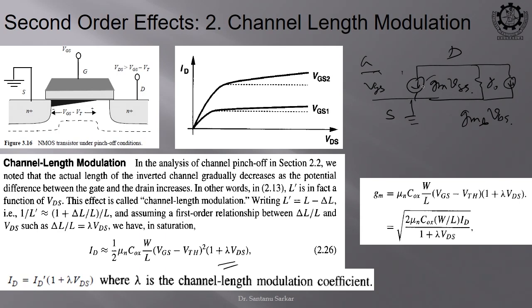So, this transconductance models our variable current source, and due to this backgate our threshold voltage is also changing. If threshold voltage is changed, your current value will also change, because your current depends on VGS minus VTH. So, if the backgate voltage modulates the threshold voltage a little bit, that means your current is also getting modulated.